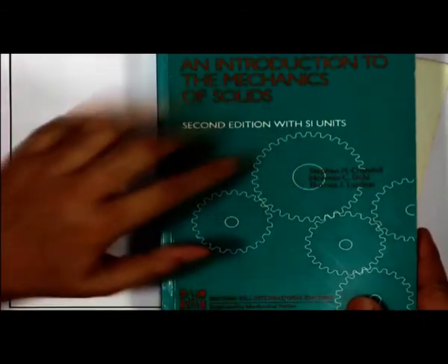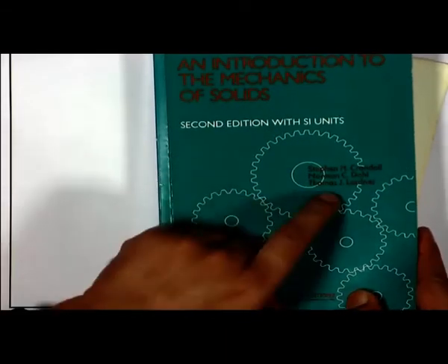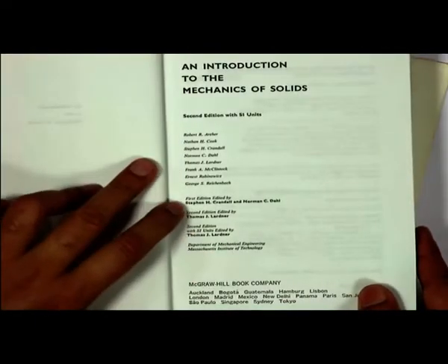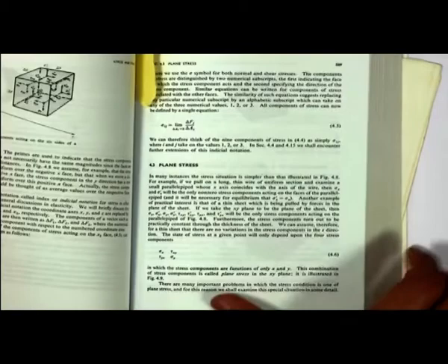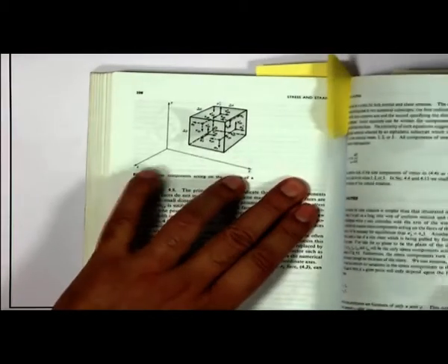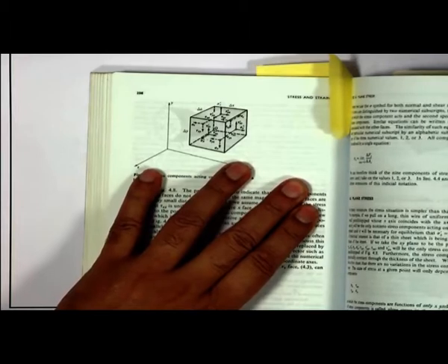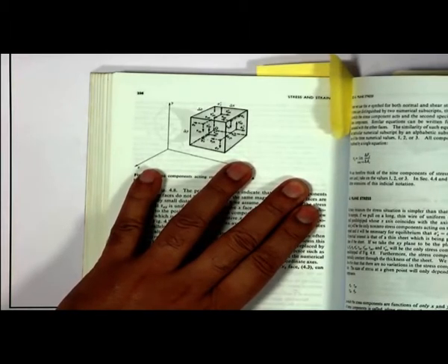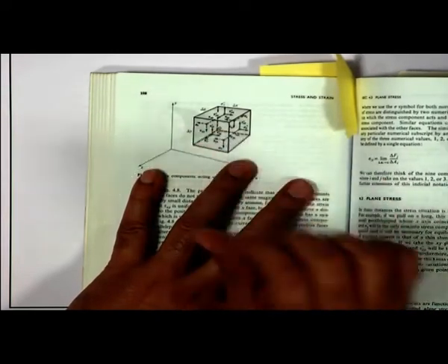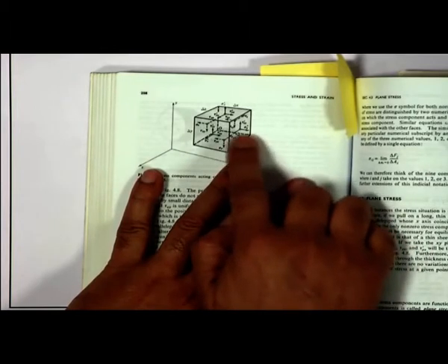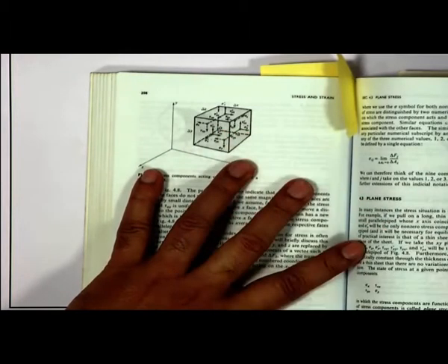Now, for that, you can focus here, I have taken one textbook. It is an old textbook, but it is very nicely explained there, of Professor Crandall, Norman and Lardner. Here are the names of the professors. You can later see it if you get an opportunity, but we will show you a diagram here. When the stresses are three-dimensional in a body, how do we represent the state of stress? Suppose this is a cuboid inside a body, and one is the normal force, another will be the shearing force, which will have two components here.